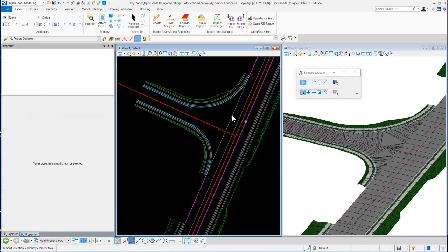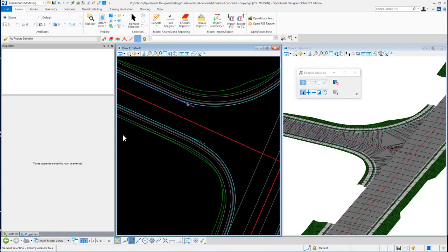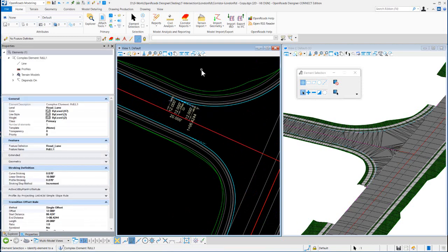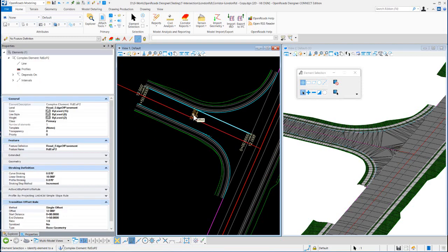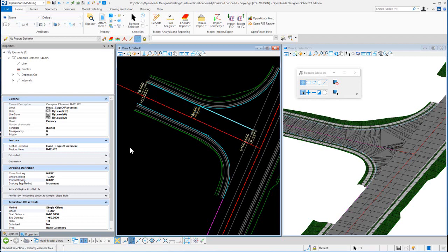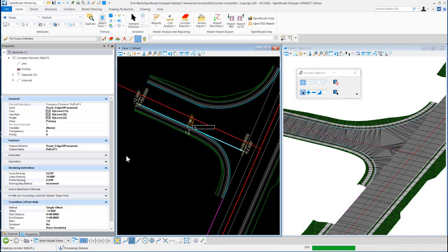The last edit I'm going to make, if you'll see these little lane lines right there. Well, let me talk about one more edit. So if I choose this element there, that's how you would control your lane width. We're going to leave it 12 feet. Well, I'll tell you what, let's make that 18. Choose that. I'm going to make that negative 18.